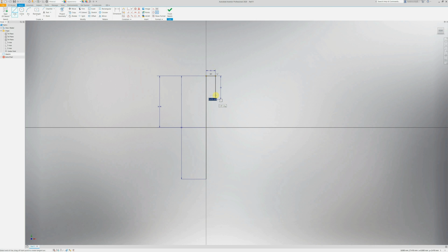So obviously 8 subtract 3 is 5mm just there, so if I come in 5mm, and then the height of that component is 60mm. Now the technical drawing shows a break line to save space on the sheet just there, but I can type in 60. And then it steps back out to a component that is 10mm in diameter. That'll be a 5mm radius, so we're stepping back out 2mm just here. And then the height of that component piece will just be 8mm, and then back in.